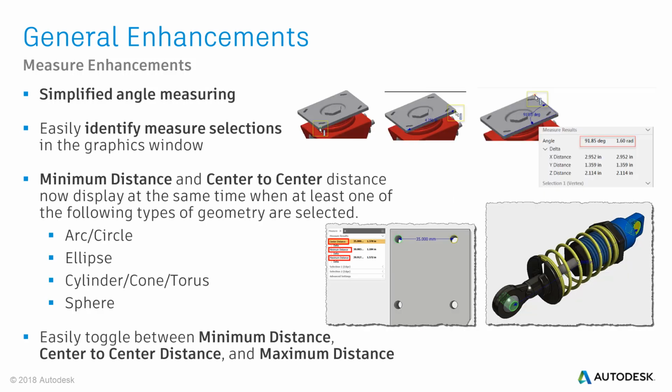Angles can be measured much easier than before. The following methods are available. Select a line or axis and then select planar faces. Or select an arc or circle to get the angle. Select two points and then hold down the Shift key and select the third point of the angle.